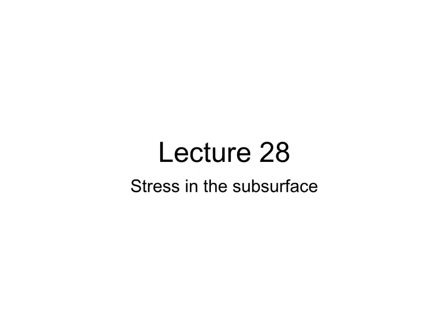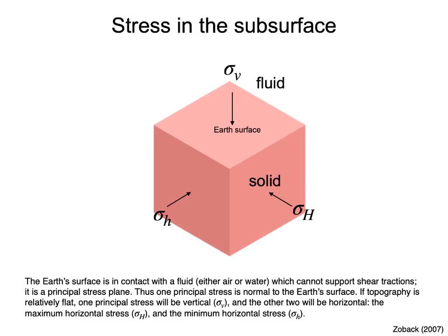Lecture 28, Stress in the Subsurface. Since the surface of the Earth is in contact with a fluid, either air or water, which cannot support shear tractions, it is a principal stress plane. Thus one principal stress is normal to the Earth's surface.